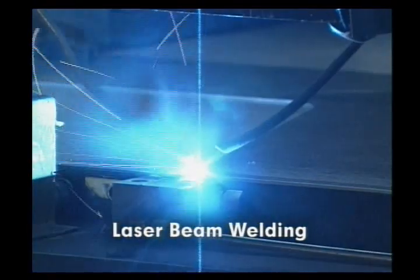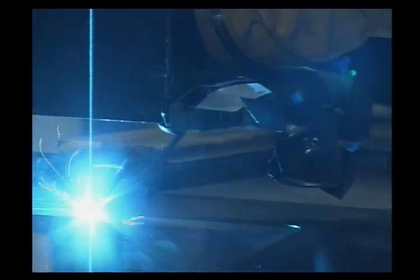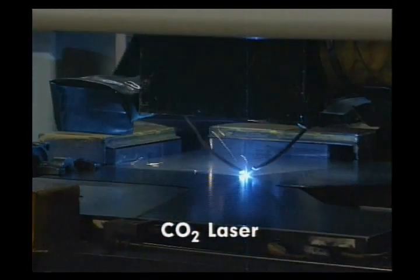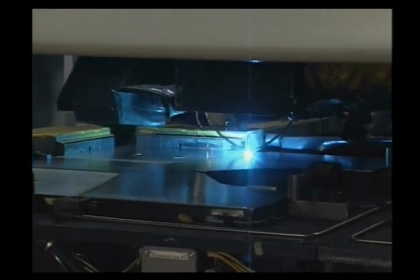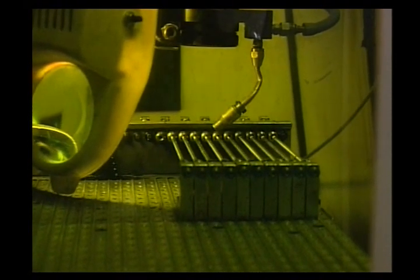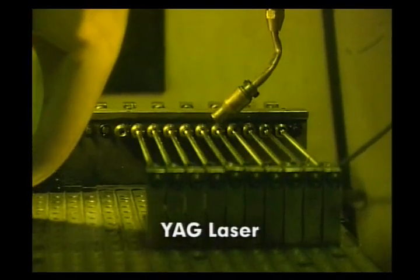In laser beam welding, the heat for coalescence is generated by a focused beam from a gas or solid-state laser. The most commonly used gas laser is the carbon dioxide or CO2 laser, which is actually a mixture of carbon dioxide, nitrogen, and helium gases. The most commonly used solid-state laser is the neodymium-doped yttrium aluminum garnet or YAG laser.